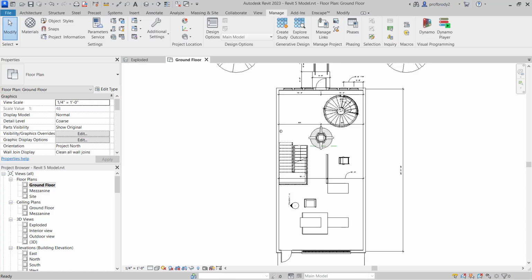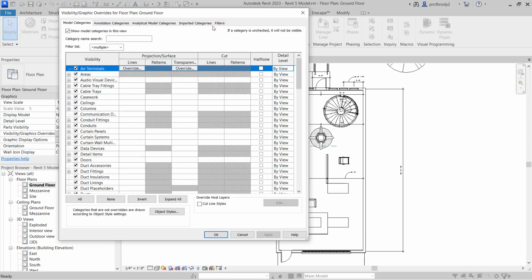Now, one thing about floor plans is they can be quite crowded, but they're also a spot where you can convey all sorts of different kinds of information. You just have to decide what you want to show. In this case, I want my mass to show up, and I also would like some kind of indication of the carpet pattern, but I don't want to make the drawing in color. Well, to the rescue comes the Visibility and Graphic Overrides menu. If you look here, it's in your Visibility View Properties. You can also type in VG to bring up that menu.